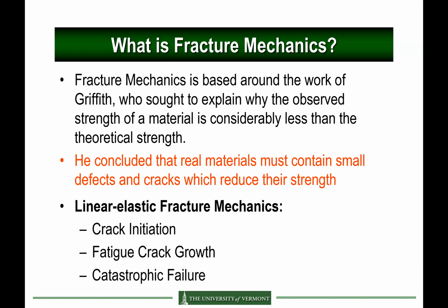So linear elastic fracture mechanics consists of three types of studies. You can look at the crack initiation, usually starting from a specimen that does not contain a crack, and look at how the crack will initiate, mostly from fatigue loading. Then you can look at the fatigue crack growth in the steady state, when the crack propagation is established by fatigue from the beginning.